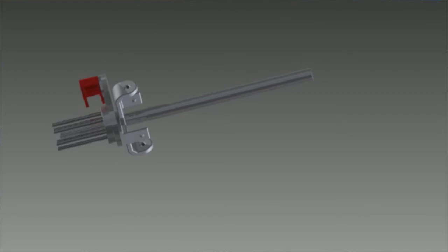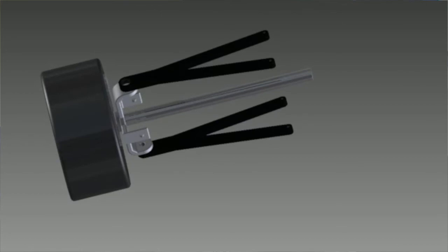One of the cool things you can do with an assembly is you can present it in a multitude of different files. Your basic presentation file just shows you a multi-view sketch of any of your parts or assemblies. One of the really cool things you can do with Inventor is you can animate your assembly. You can make your assembly move through space, put itself together, or fade into existence. Do you have anything to add to that?